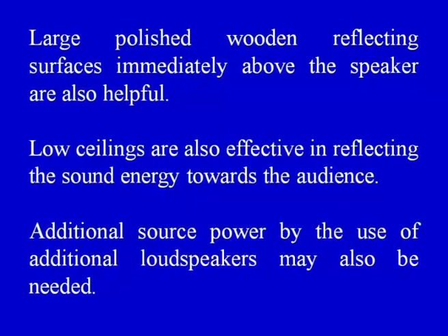This may be done by using large sounding boards behind the speaker and facing the audience. Large polished wooden reflecting surfaces immediately above the speaker are also helpful. Low ceilings are also effective in reflecting the sound energy towards the audience. Additional source power by the use of additional loudspeakers may also be needed.